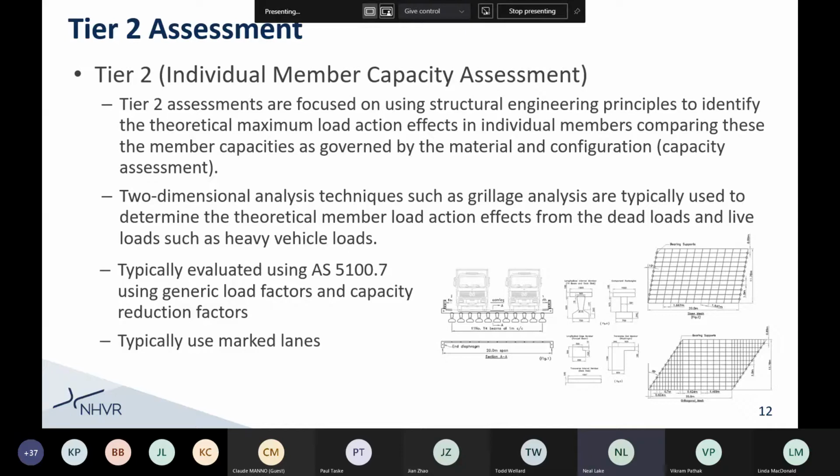When we design structures, we take a more fundamental theoretical approach, and we consider the bridge as design lanes. The use of the bridge could change over time. And so often what we do is we would jam design lanes right against the edge. If the road was earmarked to have 2 lanes, but maybe in the future it could have 3 or 4, the bridge might be wider. So when we design a bridge, we consider 4 lanes.